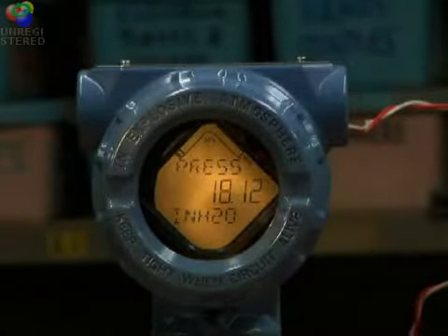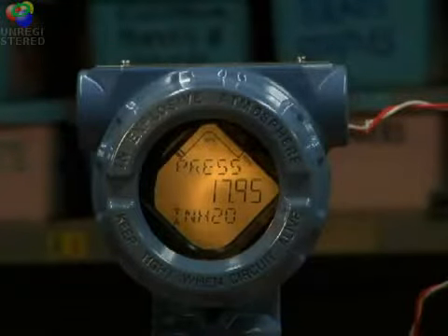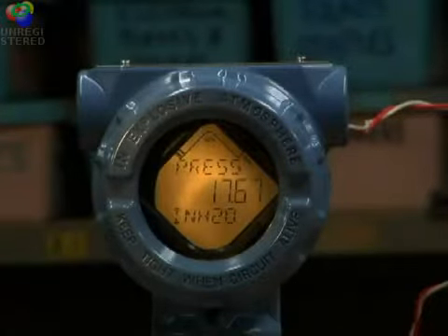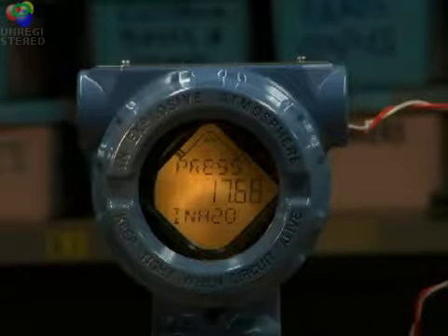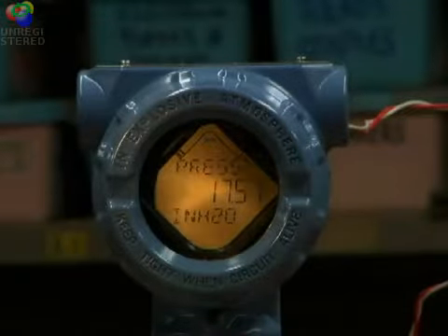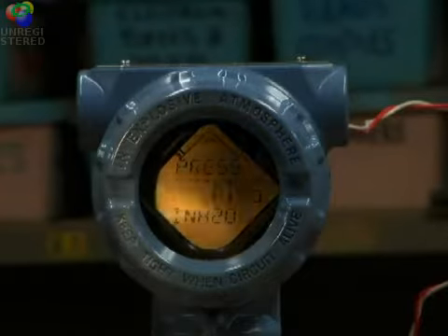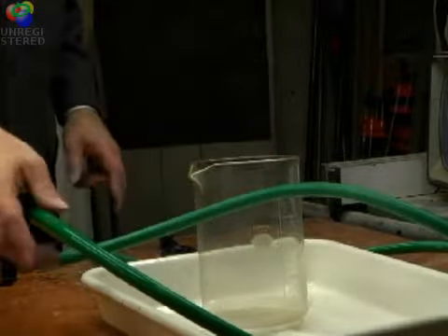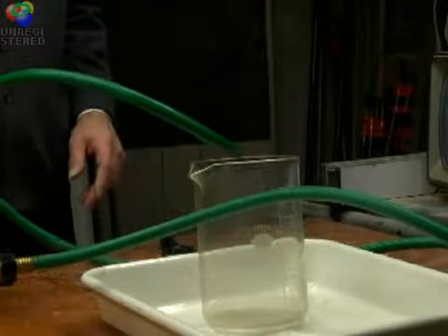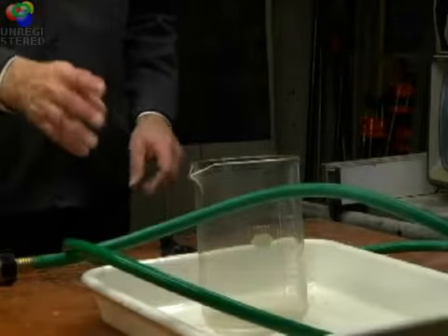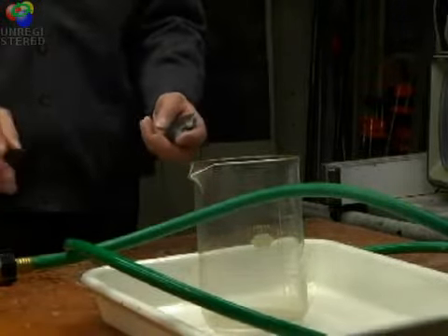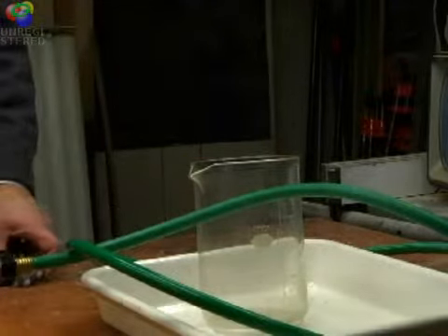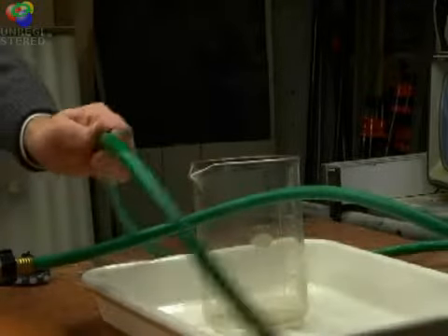So it jumps to just over, right about 18 inches of water with the flow what it is. Now that really doesn't tell us anything because we really don't know what is going through the pipe at this time. So let's try a little calibration. Over here what I have is a nice 2-liter beaker, and I'm going to use the hose to feed into that, and as soon as the flow gets stabilized, we'll use a stopwatch to measure how long it takes to fill the 2-liter beaker, and that will allow us to calculate the flow rate. So let's turn this on and see what happens.